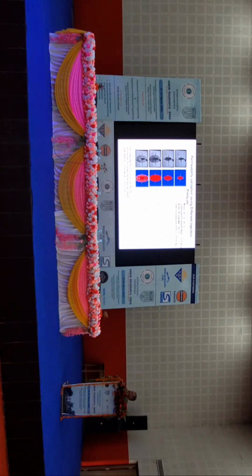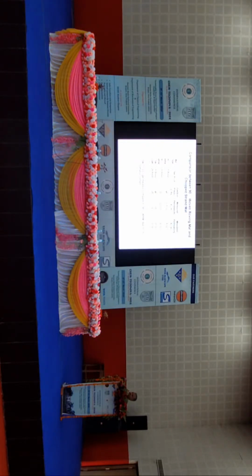Next one please. I also worked out different injection pressures. I just wanted to see whether the permeability data varies with respect to injection pressure, but it is the same. So you are getting the ideal permeability, which we can call the effective permeability. Next one. This is a comparison between different mats at different pressures.